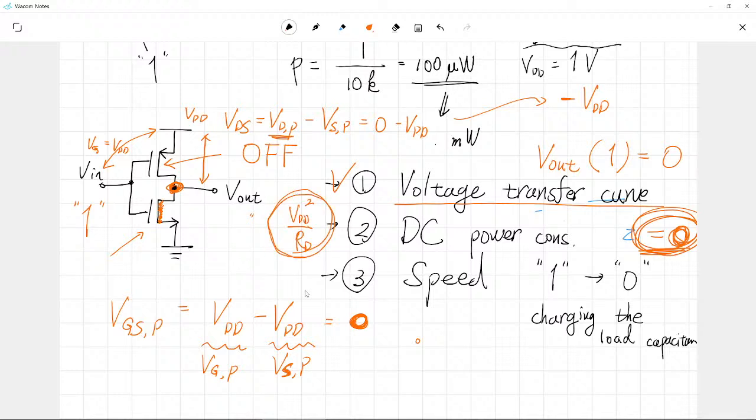That was its power consumption. However, now you have almost 0 power consumption. So that's the reason why we have to use CMOS technology. Otherwise, we cannot live with this high DC power consumption originating from NMOS-only technology. Okay, so do you have any question? This point is quite important. No DC power consumption. That's good. That is actually the thing we have to realize.